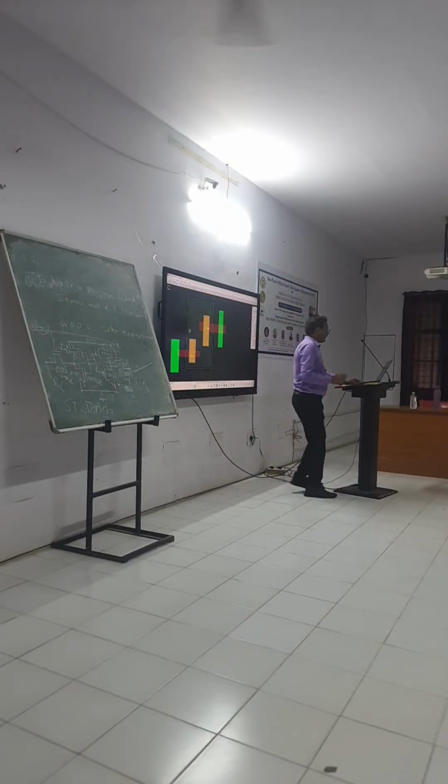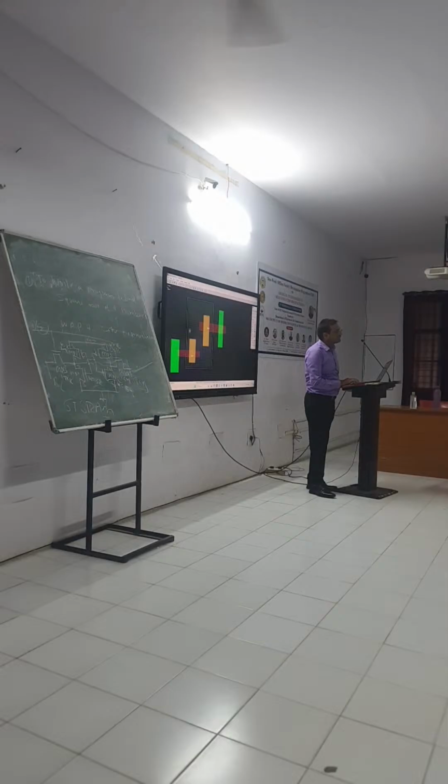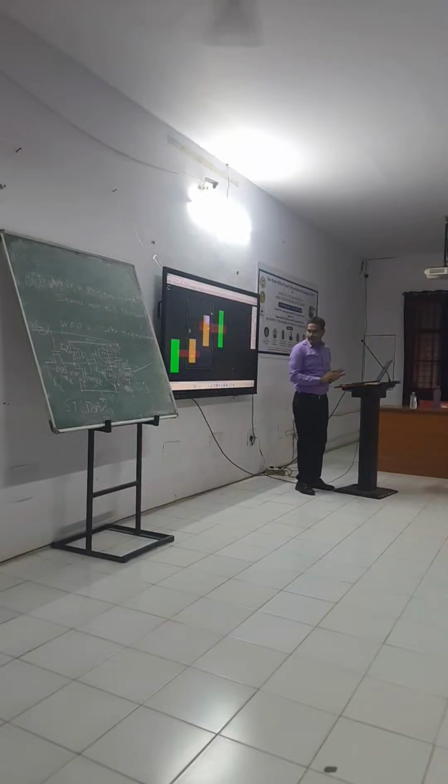So what you do? Here VDD you can give. So VDD means one metal contact. So in top you can see metal contact. So here we will keep one. So its name you can give VDD. Get it? So terminal name should be proper, then there will be no confusion. VDD. Okay, one VDD given. So that is the source.